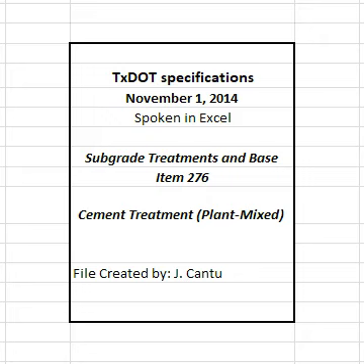The roller must travel at a speed of 2 miles per hour, vibrating at maximum amplitude, and make 2 to 4 passes with 100% coverage exclusive of the outside 1 foot of the surface crown, unless otherwise directed by the engineer. Additional passes may be required to achieve the desired crack pattern as directed. Notify the engineer 24 hours before the microcracking begins.